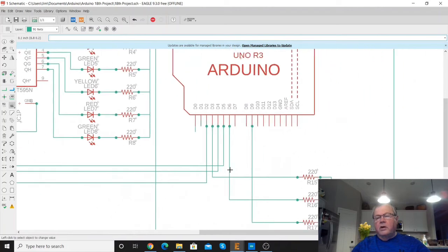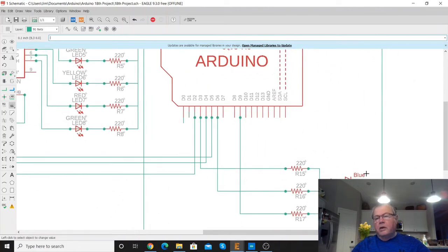And then we have an RGB LED. And these are all current limited by 220 ohm resistors. Same with our other LEDs. They're all current limited with 220 ohm resistors. And the RGB is controlled by 3 different pins on the Arduino. And we want those controlled by pulse width modulating capable pins. So we can pulse width modulate the signal to the RGB to get different colors.